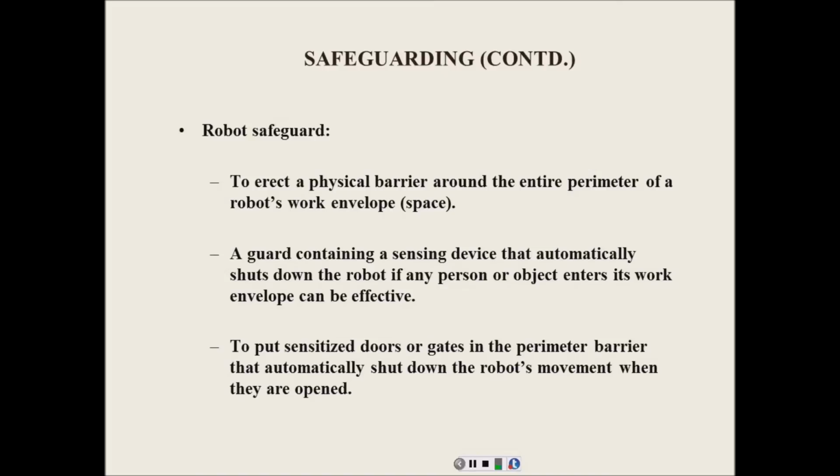Okay, you understand that? So if we say 30%, everybody else's robot, if they put it on 30%, that will be 30% with a maximum of 250 millimeters per second. On the KUKA, if you put it at 30%, it's going to be 30% of 250 millimeters per second. So what that means is, to not spend all day and have the ability to do the same labs that everybody else does, when you go to the teach mode on that robot, you'll have to put it on high-speed teach.